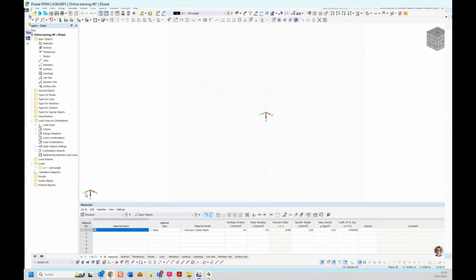How I say it's connected to the global axis system. So you see the Y direction when I click on the Y, or when I go to the X. The same idea is here with views in X, Y, Z, or you can choose other directions here. Another option is when you press Control and the middle mouse button, you can also turn around here. Okay, but let's start with the modeling.